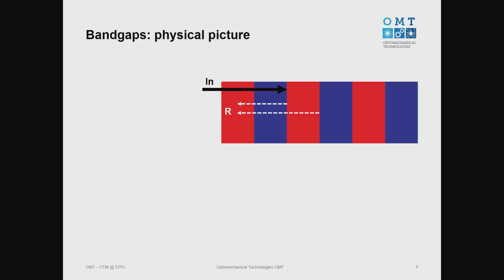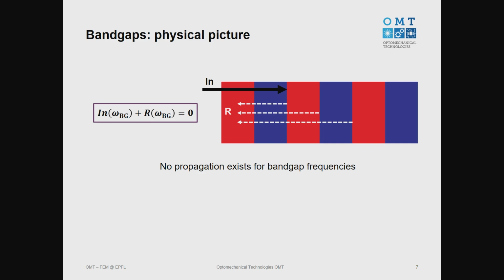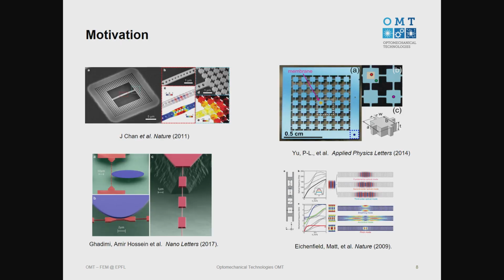And also here, the idea of optomechanical crystals, they also work with the band gap, something that Professor Marquardt already explained to us in the Erlangen workshop, if you participated. And also this work from our group, where we have a doubly clamped beam with a micro disc, and we use these periodic structures called phononic crystals in order to shield the radiation modes.